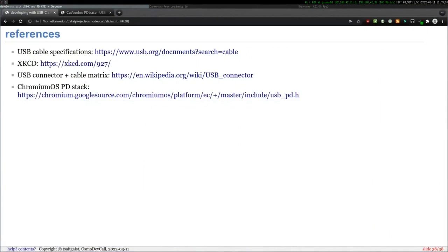So this is debug hardware. You see there are tons of pins which you don't require for not debugging. And if you still want to play, most of the USB Type-C controllers speak I2C. So you can just use this. They are QFN or BGA most of the time because they have to be really tiny. And you can actually re-implement that.